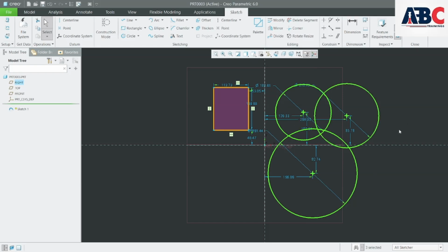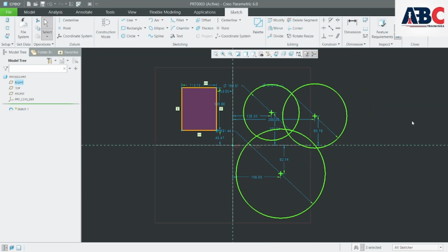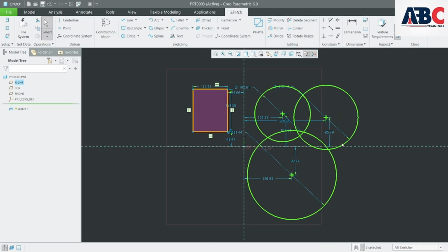Now pressing shift and this, you can pan this. Now see it's off actually. When I click this on, it highlights what? It highlights this section only, whatever the intersection point is, like overlapping geometry. All these circles are overlapping each other, that's why it's highlighting it.